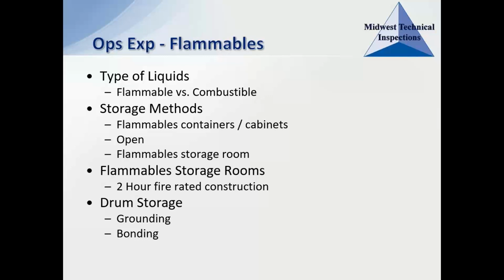So that room should either have a recessed floor, so that if there's a spill, it's not going to spill out beneath the entry door into the main area, or just some sort of lip at that door to keep it from spilling out into the outside area. And there cannot be any outlets or switches or potential electrical arcs or sparks inside of that storage room. So there's a lot of criteria involved with that storage room. It's a pretty serious undertaking for that process.